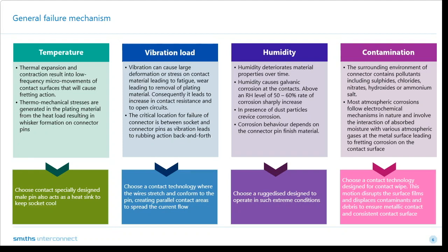It can be temperature, and by temperature I mean the thermal expansion and contraction that results in low frequency micro movement of the contact surface. And that will cause fretting action. And what does the fretting action do? I will cover that in one of the next slides. This sort of movement creates some form of mechanical stress, and it creates deterioration within the contact and therefore the performance of the connector.